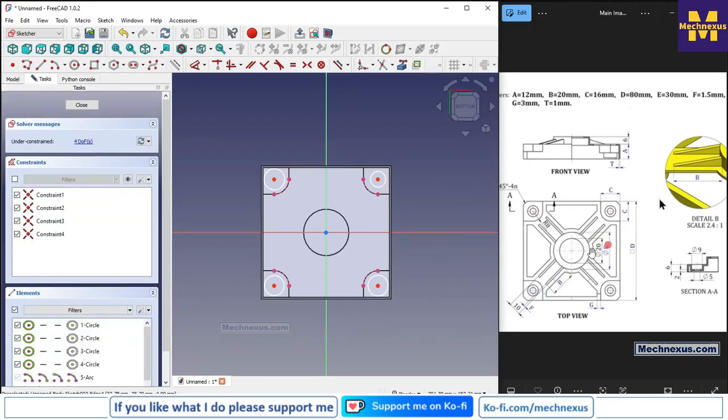Here this is of diameter 11. Select a smart dimension, give it 11 mm. Select all 4 circles and make it equal.